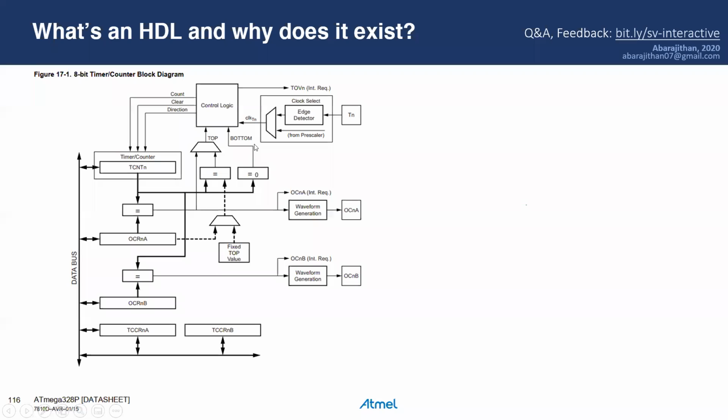So what is inside the IC? What you see here is a multiplexer, that's a comparator, and this is a data bus. So this is basically a digital circuit. Not only this, but all processors, GPUs, and ASICs, application specific ICs, any kind of digital chip you find is a digital circuit. It has all these multiplexers and these kinds of things inside.